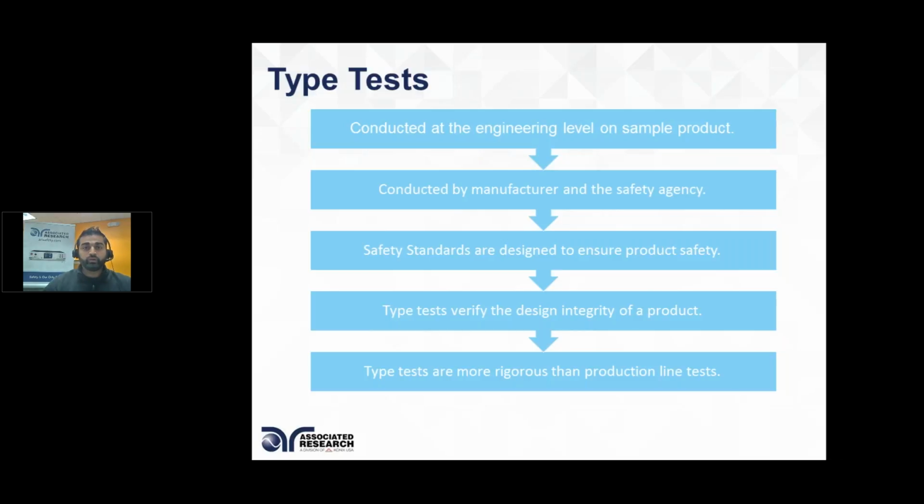Normally the line voltage is powering up your DUT, and you want to make sure none of the current that's used by the product is passed on to the surface of the product, or if there's a fault condition inside your product, it doesn't cause any kind of live dangerous situation where a shock hazard could happen. So these are the things you're checking during your type testing, to ensure that if a fault, such as a short circuit, were to happen inside your device, it doesn't endanger the end user.